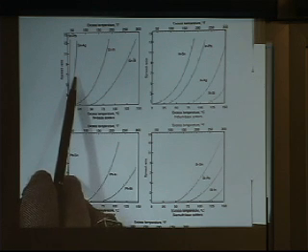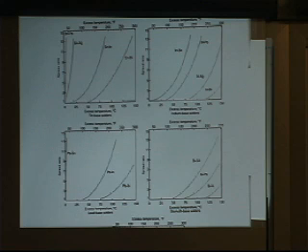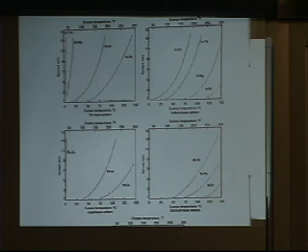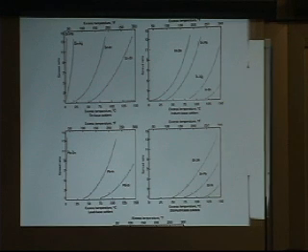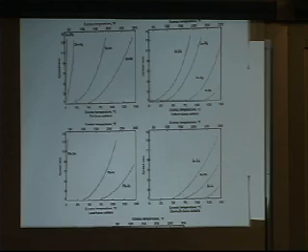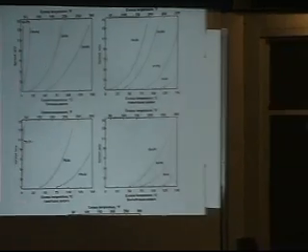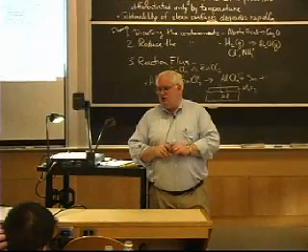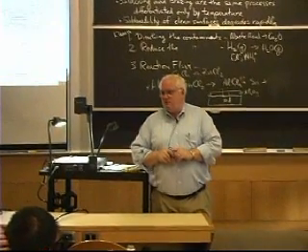I think it's 95 tin, 5 silver, and the plumbers hate it. In the old days, the plumbers used to plumb up some part of a building and have 100 joints, and they'd have maybe 1 leak out of 3 jobs. So they might get 1 leaking when they pressure tested it or leak tested it. They'd have one part in 300 as leaks. Now they can do 100 joints on a job, and they can expect 5 or 6 leaks.